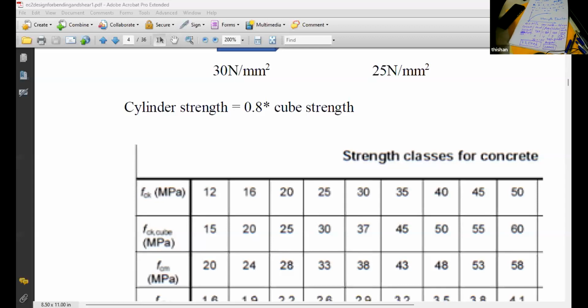Pre-stressed concrete members are thin sections, whereas reinforced concrete are massive sections. So in reinforced concrete construction, you can use fly ash, but even for pre-stressed concrete, you can use fly ash to reduce the cost of construction. Because it gives a very nice finish with a very good cover zone that is resistant to chlorides and sulfate. So in highway bridges, it's worth using 15% fly ash.